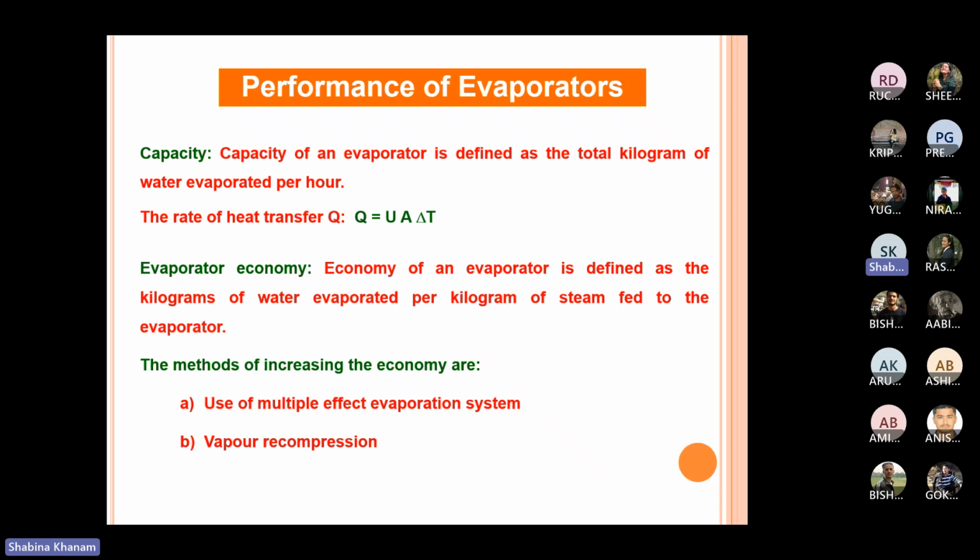Okay, so flashing is to generate vapor and liquid at low pressure in comparison to the inlet. Because the condensate of vapor will not be utilized anywhere, we will produce low temperature vapor and low temperature liquid from it by flashing, and that low temperature vapor is used as a heating media in downstream effects.